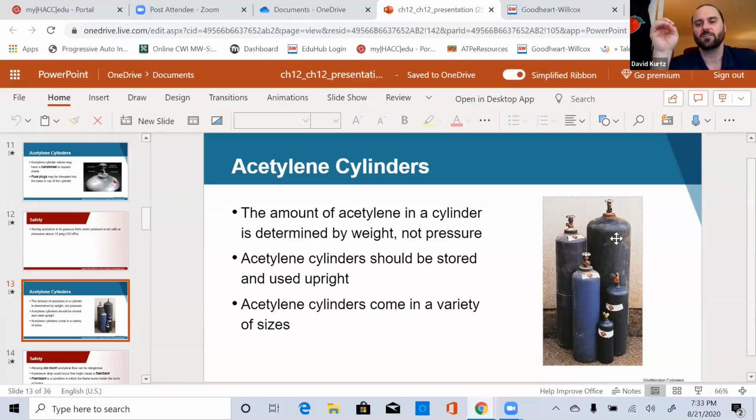because especially when you're cutting, not so much when you're welding, your PSI for acetylene will be 3, and for oxygen it'll be around 3.5 to 3. When you're cutting, your acetylene's usually about the same, but then your oxygen, for instance, we'll be using at 30 PSI as opposed to the 3 PSI. So you're using almost 10 times more oxygen to cut with than acetylene. So usually it's about almost 2 to 1, you'll use your oxygen over acetylene.